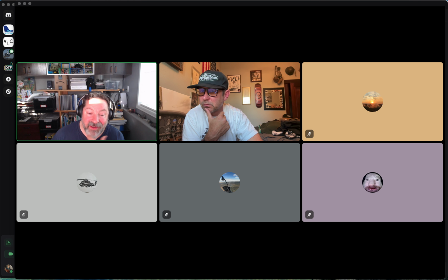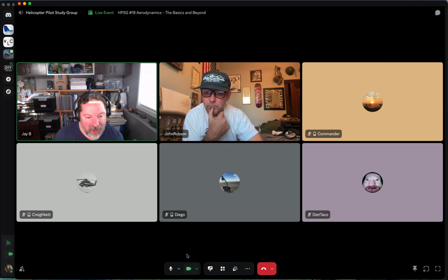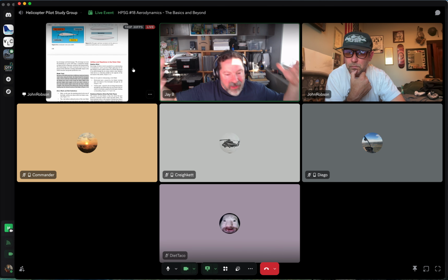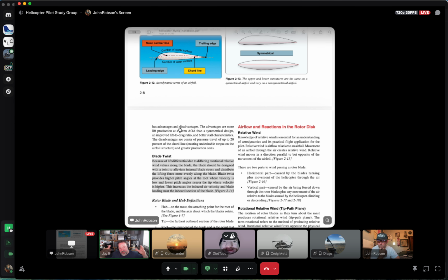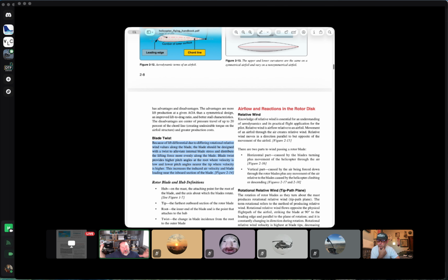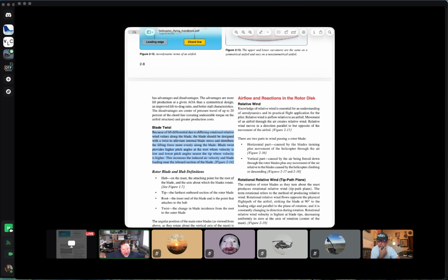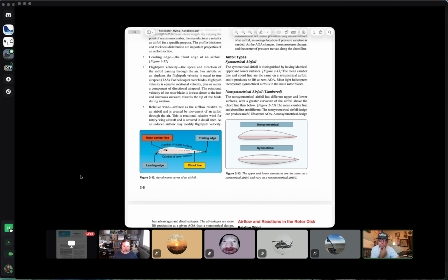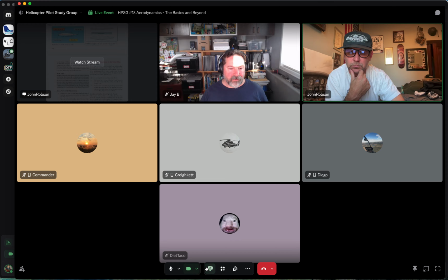Yeah, that's again, John, that's great insight. This is the great thing about this discussion group, between all of us, we bring up ideas that people have never thought of before. I really like that idea. That's exactly what's probably happening: there's an unequal lift across the rotor. At some point there's negative, and some point there's equal, and some point there's probably a little bit of lift, and that might be why we're seeing vegetation moving, even when the collective's all the way down. Great ideas. Yeah, good stuff.